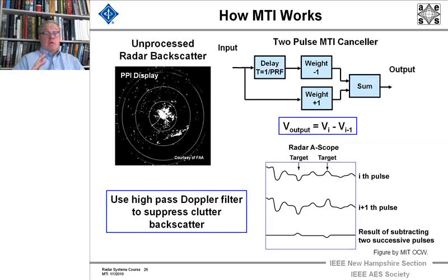It is an analog display in which the gain is set so that targets just above the noise level of the receiver show up as white dots. So these aren't noise detections. They might be 5 sigma noise detections because there's a fluctuation. Noise is a random process. But you see black, no targets are there.